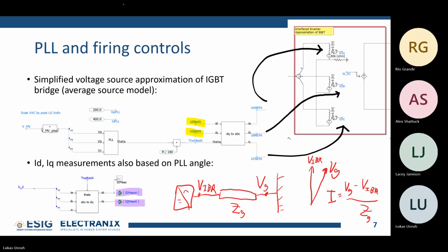This is a very extreme example, but let's say it moves somewhere over here. Immediately, if we assume that the inverter angle isn't changing, we get a huge increase in the amount of current. We had this little one before, and once this angle changes, we are looking at more like this. So it's a huge jump in current if we don't do anything.